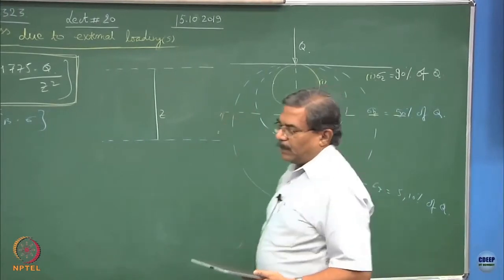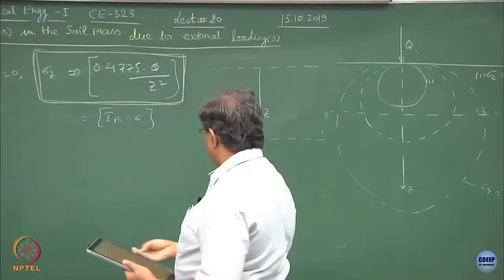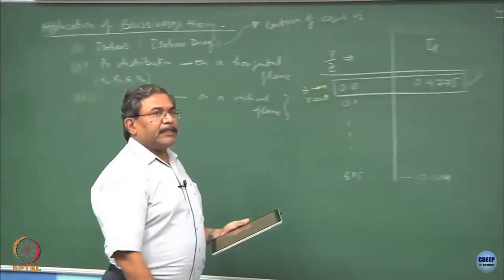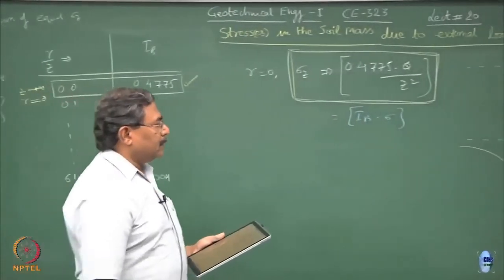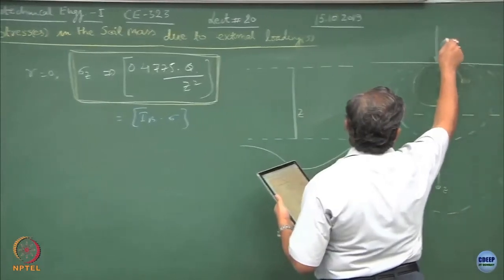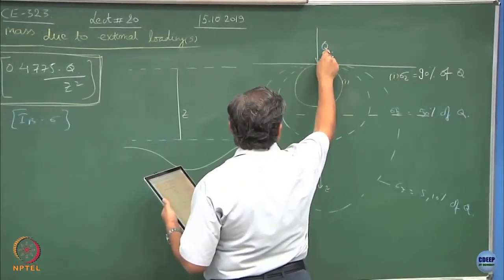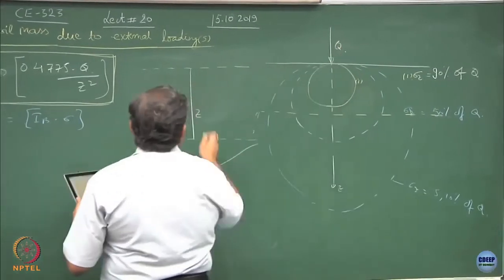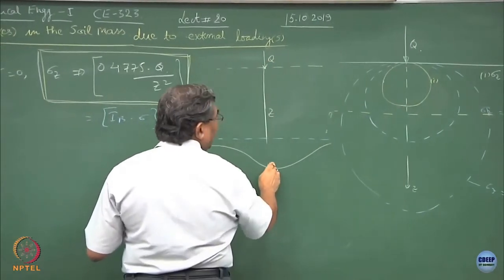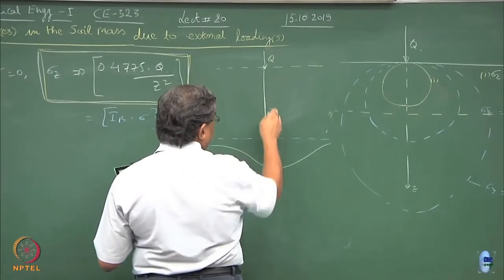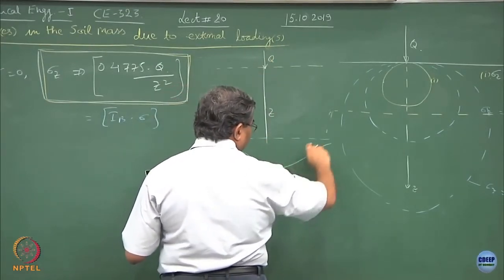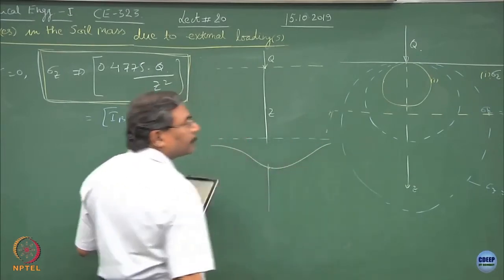So, if there is a plane which is passing, this is the same plane as what I am showing over here. So, the pressure distribution would be like this. Why does the rutting of pavements take place? This is the answer. Excessive loading, the tire pressure from the vehicles, creates the maximum intensity of the pressure at a certain distance Z, just below the point of application, and beyond which it fades out.